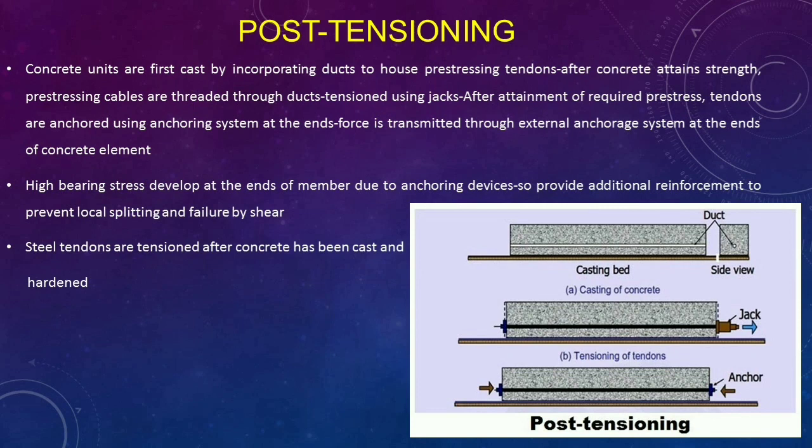Additional reinforcement has to be provided to prevent local splitting and failure by shear at the end, as excessive bearing stresses will be produced at the end of members due to anchoring devices.